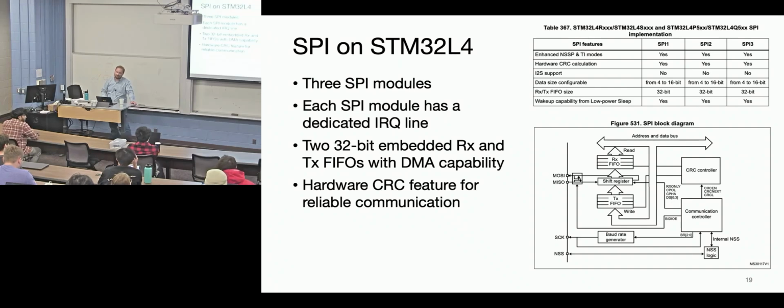Okay. I could see that, though we could find counterexamples too, where you're like, this chip won't respond because I haven't selected it. So I'll have one clock speed for one chip, and then when I select a different one, I'll switch to a different clock speed. But that's also complicated and maybe has other unintended consequences. So that works. Maybe one peripheral wants to use SPI, but you want to access it at the same time as another peripheral. So having 3 modules lets you access 3 at the same time. Okay, you're thinking about time as a commodity. That's good. Any other reasons?